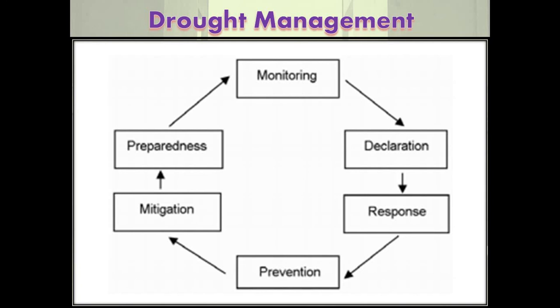Next, drought management. Many of the management alternatives available to water suppliers to prepare for and respond to drought events fall into two broad categories. First is demand management and second is supply management. In demand management: public information and education campaigns, emergency conservation programs, water service restrictions on non-essential uses of water, prohibitions of selected commercial uses, drought emergency pricing, water rationing programs. Augmentation, improvements in water supplies, for example leak detection, lining of transmission canals, etc.